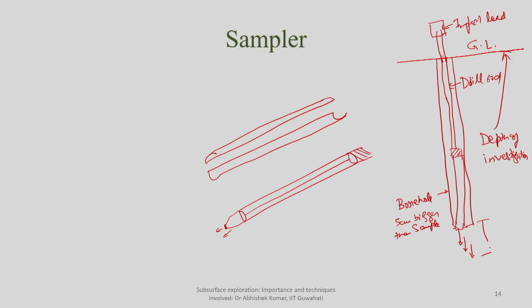Finally, when the entire push equals 150 mm, you can mark 150, 300, 450 here, since this part will be below the ground surface. So you apply three markings at 150 mm intervals. Once your sampler has pushed 150 mm into the ground, you record how many blows there are. So this is about the sampler.